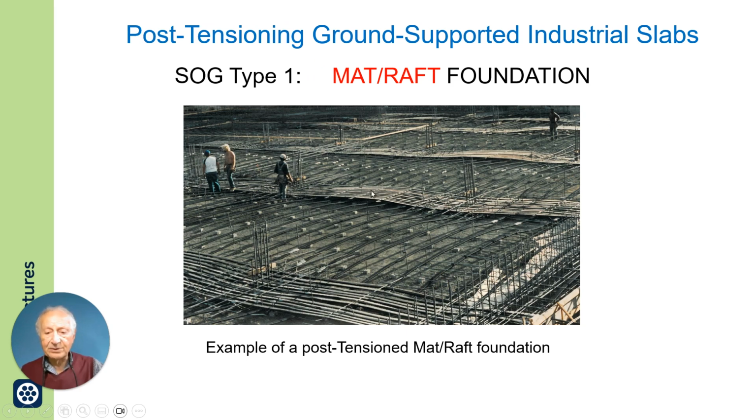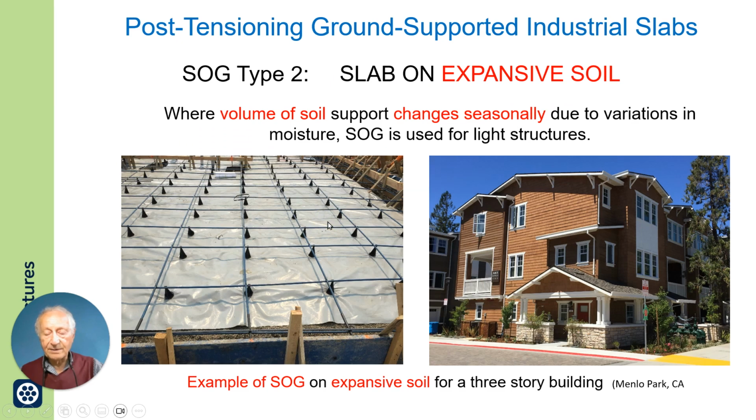Here is an example view of a raft foundation. Observe that below the column the tendons are low, and at midspan between the columns the tendon is high, so it can push down the load picked from the two sides.